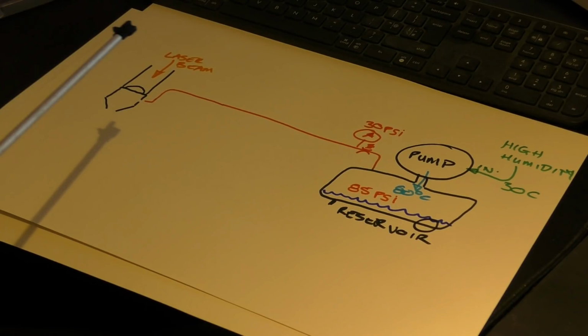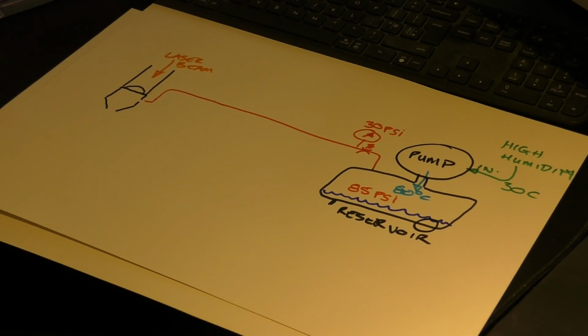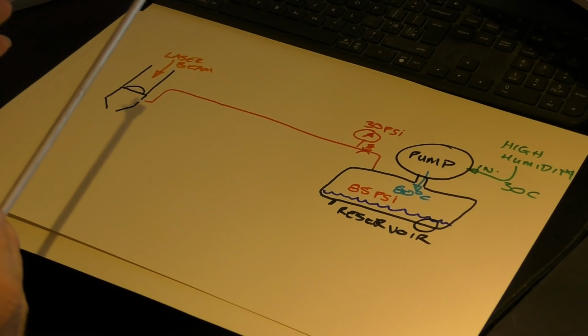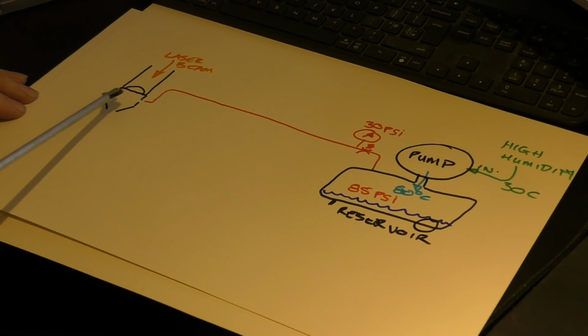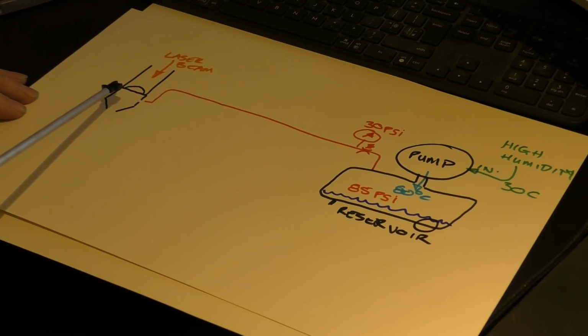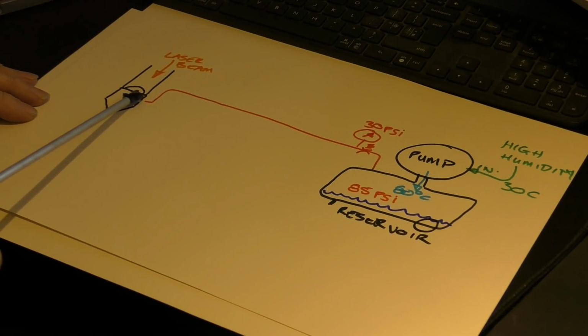I'll bring you back to something we spoke about earlier. Steam, solid particles. Laser beam loves to hit solid particles. This is water vapour. These are solid particles of water, little micro droplets, but they will be reheated up in here by the laser beam. And as they heat up, they will drift towards the top and sit on the face of the lens. And there will be eventually some crud that actually bakes onto the face of that lens, because we've got a little oven in here, a little superheated water oven. And that's basically what happened to my lenses.